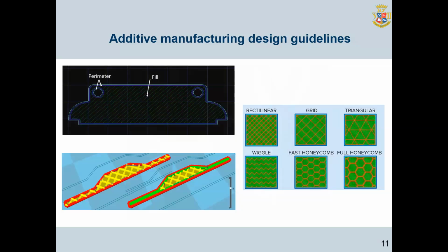The resolution of printing is determined by the diameter of the nozzle. To obtain sufficient strength of the model and reliable fusion of plastic, printer manufacturers recommend making the outline of the object in two passes. Each layer consists of a perimeter and of fill. The model may have a different percentage of filling, and there may not be a fill for a hollow model.